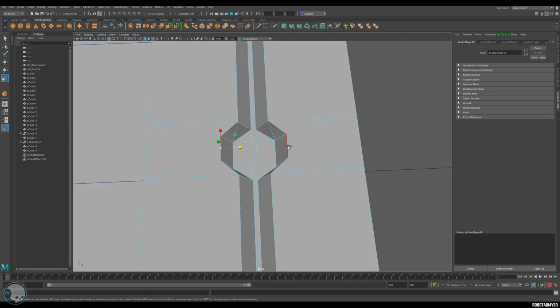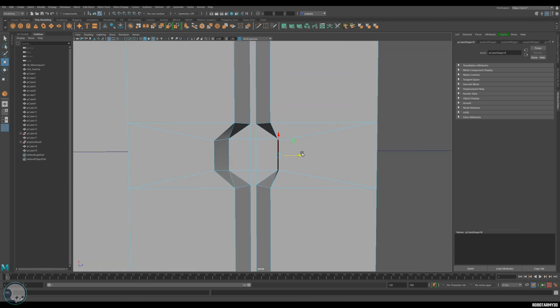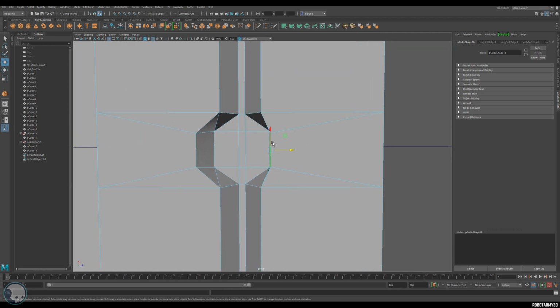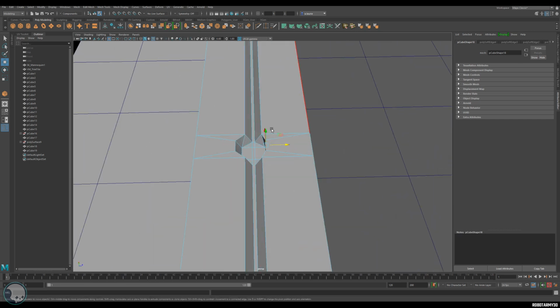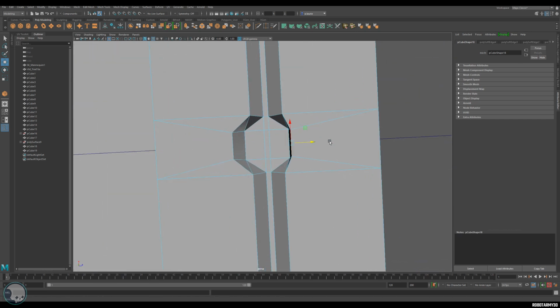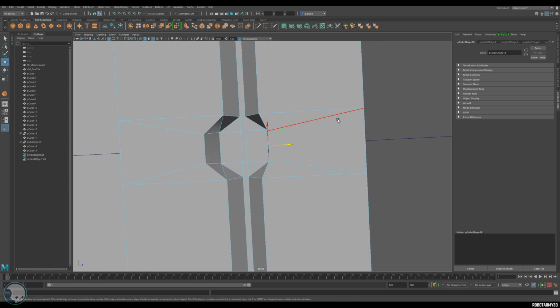Now, with any details that you do, any bevels that you do, never do them at a 90-degree angle. So if we've got this angle here, if we just go like that, what will happen is when we bake that down in Substance Painter, it's only going to bake the rays exactly down towards that normal, which is the underlying trim sheet. So this flat plane, it's only going to go in one direction. So anything like that has no edge whatsoever, you will not be able to see it.